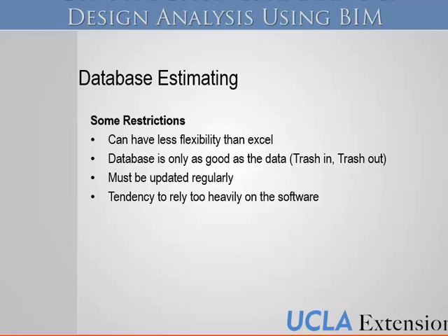You mentioned a soils report. Now, as the estimator, are you in charge to review the soils report to account for any possible costs coming through? Definitely. So let's say you got an old report because the owner didn't want to pay for an updated soils report, so you went with that, and during construction you have a bunch of boulders that were not there from the other report, that magically appear over time.